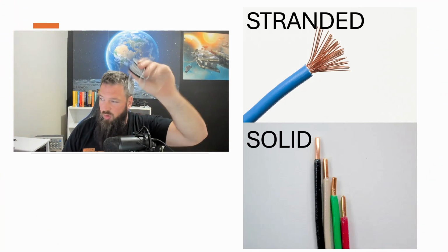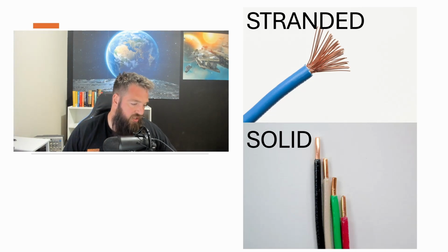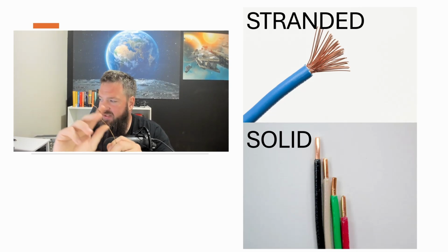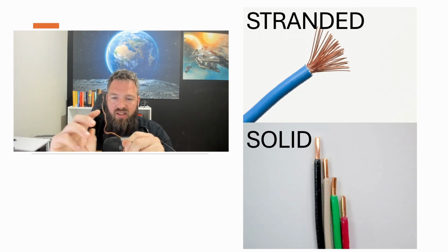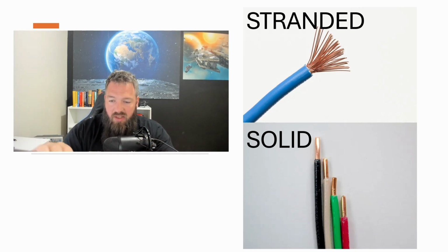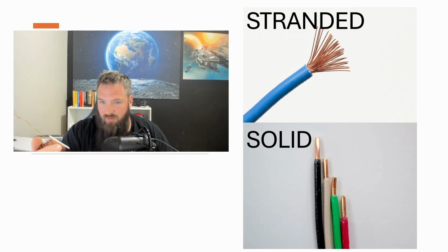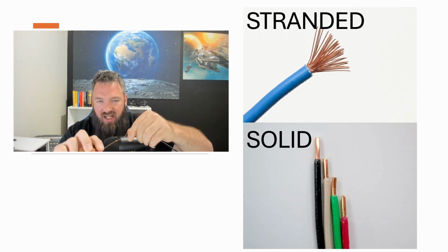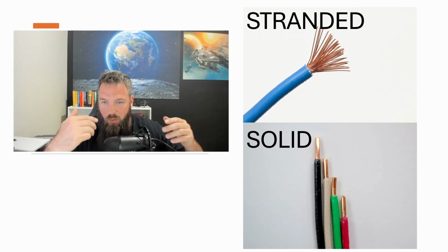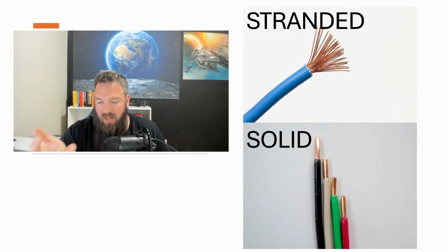Then you have solid wire, which is more expensive. This is one solid piece as shown, and it's not as flexible as the other wires. After you bend it in the same spot once or twice, you can't bend it again, because that's how the wire works. So it's not a good application if it's for automotive, because over time, the constant vibration will end up breaking this little single piece or reducing the current carrying capability.